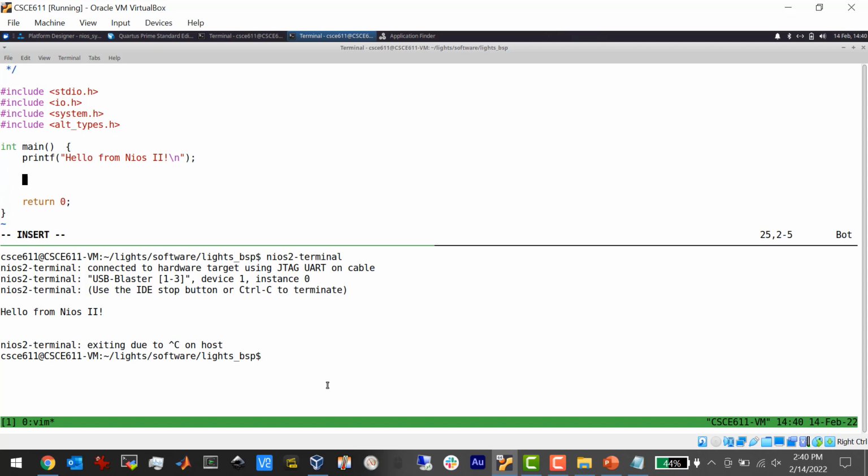Okay, so now another easy trap to get in, well, first of all, your embedded software is generally going to run an infinite loop. If you ever did any Arduino type design with the Arduino IDE, you don't have to put a loop in there, but there's actually a function called loop, which you can fill in, and then that is actually in an infinite loop, but the loop is structured externally to that function. In this case, we have to put the loop in.